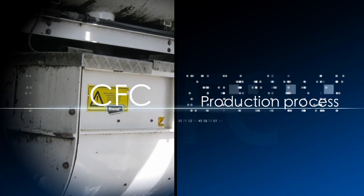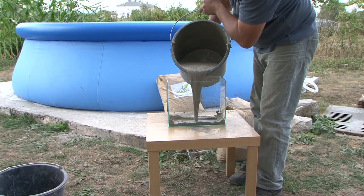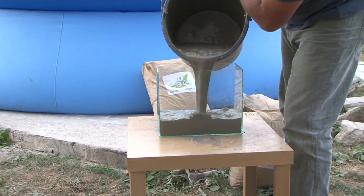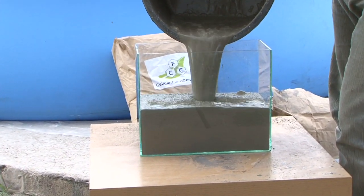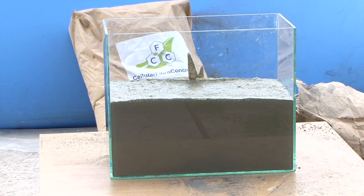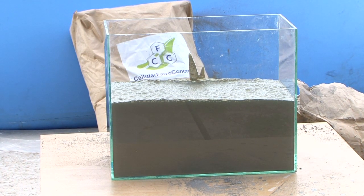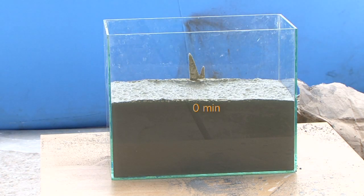Production process. For the production of foam concrete, cement, filler, and a stable foam prepared in advance are mechanically mixed. The difference in the preparation of foam concrete and gas concrete is that the latter is produced with the help of a chemical reaction, which generates hydrogen bubbles, creating many tiny spherical cells in the limestone, cement, sand mixture.